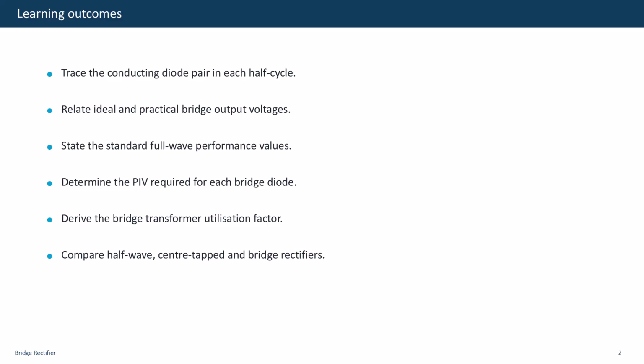You should determine the peak inverse voltage across each non-conducting diode. You should also recall the standard full-wave values for average output, RMS output, ripple factor, and maximum rectification efficiency. Finally, you should be able to derive and interpret the transformer utilization factor of an ideal bridge rectifier.